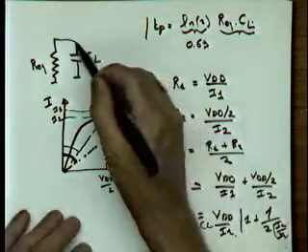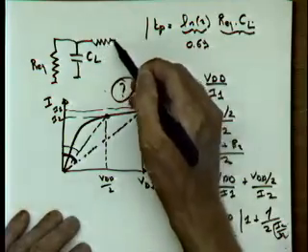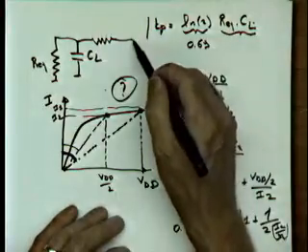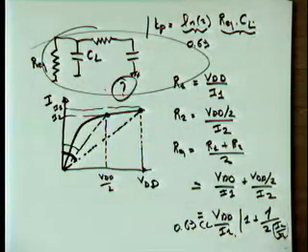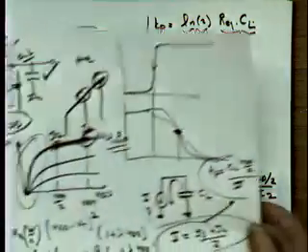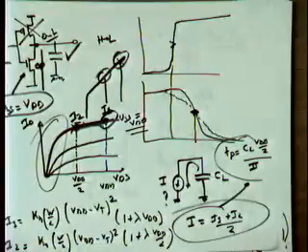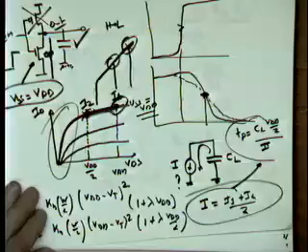But as I said, the advantage of this approach is that if I now connect a wire to this, which has a resistance, I just keep on adding the wire. And if I have some more logic circuits loading it, I can have more capacitance connected to it. The whole thing becomes a large RC network, and those things are easy to evaluate. That's why I like the resistive equivalent. But in certain circumstances, you look at your problem and say, hey, I know how to compute I1 and I2 very easily. I can see it. Use this way. It's a lot easier. So pick the approach that you think is going to be the easiest for you.